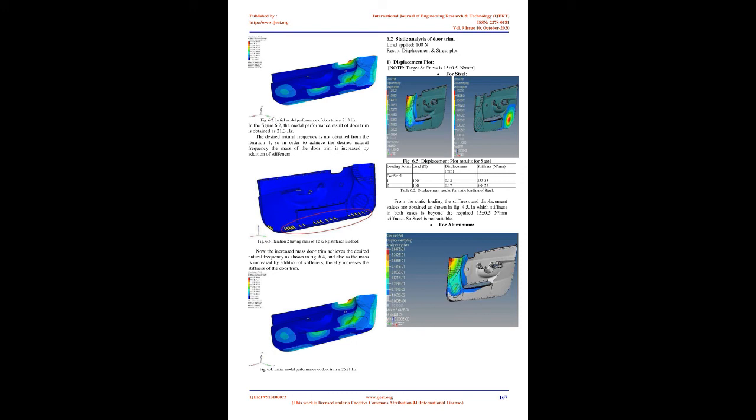5. Methodology. 5.1 Meshing parameters considered for door trim analysis. The elements used for meshing the door trim have a size of 5 mm, and the remaining quality parameters are explained in table number 2. To properly represent the CAD, both quad and tria elements are used for meshing. These 2D shell elements have only translational DOF, and there is no rotational DOF. Information for solid elements will be provided below.